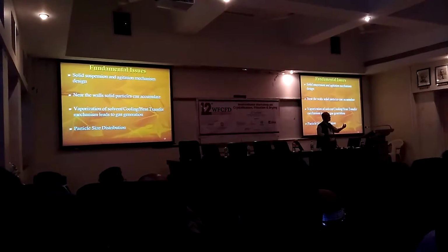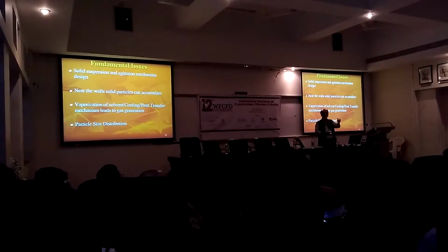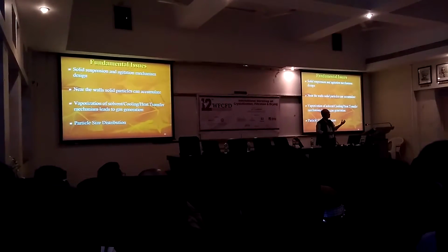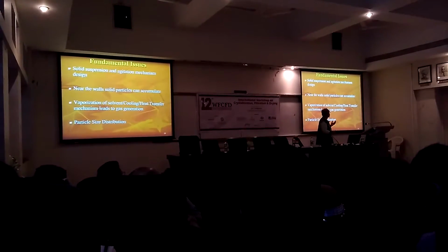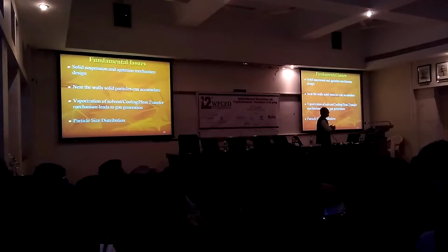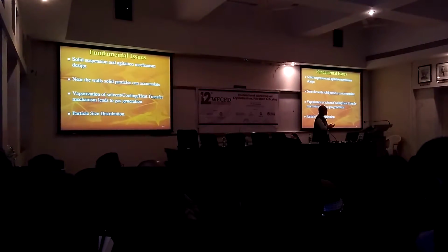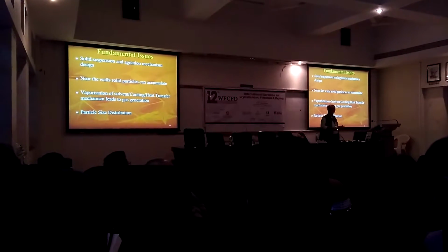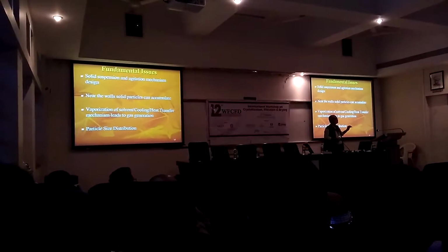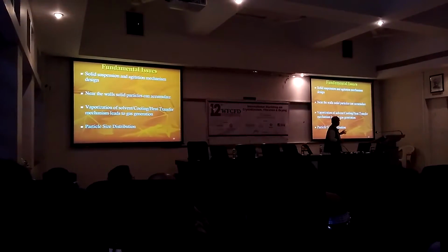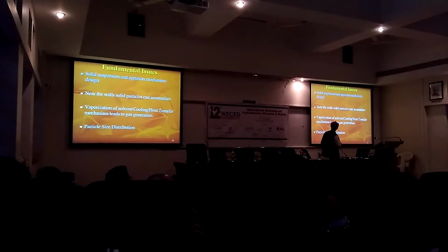So you need to handle these gas liquid solid systems and arrive at appropriate impeller type and impeller operating speed so that the system is capable of taking care of this vapor which is getting formed. Ultimately, when you are able to achieve all these three, the resultant product has to have a specific size distribution. So depending upon the time available, we will talk about how the crystal size distribution can be obtained. If not in this lecture, in next lecture, we will definitely talk about that.